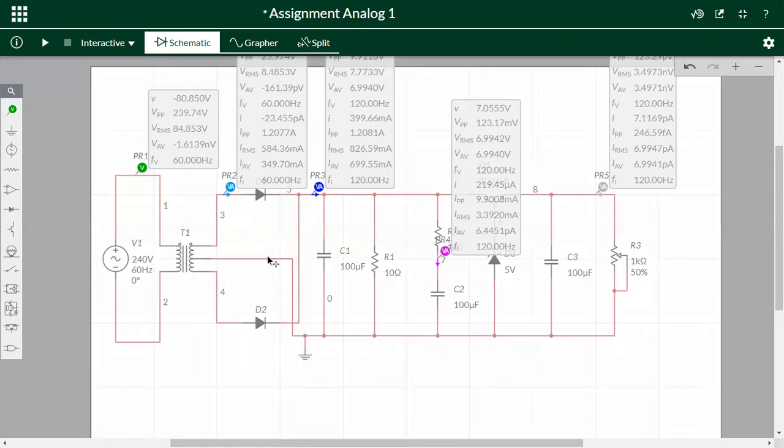The capacitor in the circuit is not charged fully, so the charging of this doesn't occur instantly. Once the voltage supply becomes greater than the voltage of the capacitor, it gets charging. In both half cycles, the flow of current will be in the same direction across the RL load resistor. For the Zener diode connection and waveform, Jason will proceed.